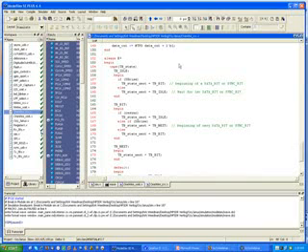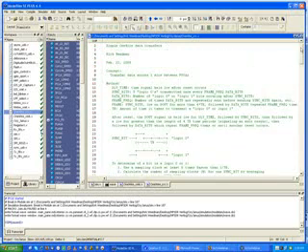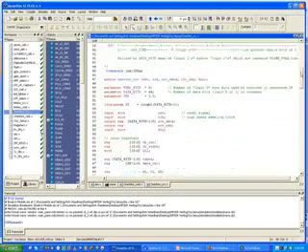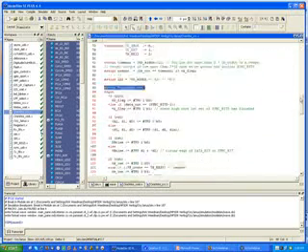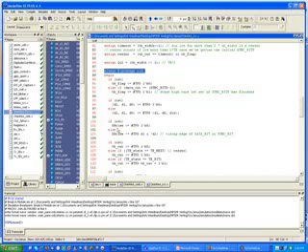So anyway, the way this works is if I'm in idle, I wait for the signal called dB rise before I go to bit. Okay, so what is dB rise? Well, dB rise is just a 1 clock wide pulse that occurs at the rising edge of a data bit or a sync bit. So how do I create that?